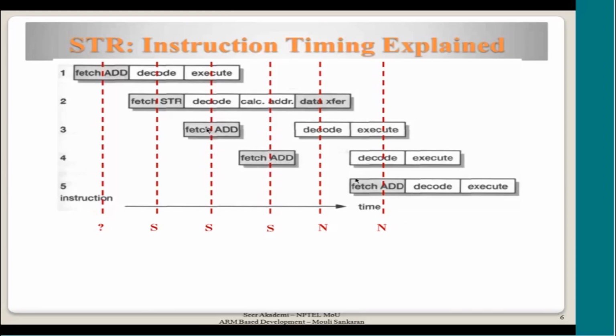Remember that not every fetch is going to give you S only. Only when the previous access is also an instruction is the sequential access maintained. So the memory will be able to provide the data much faster than in a non-sequential cycle.